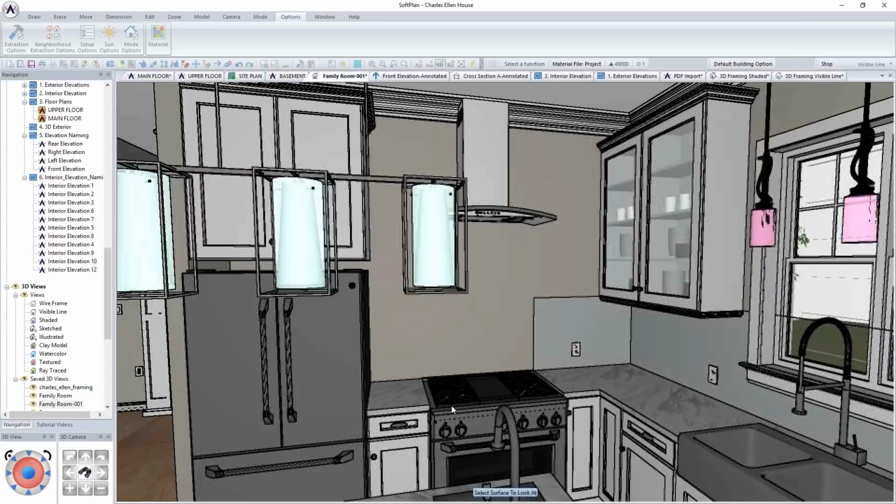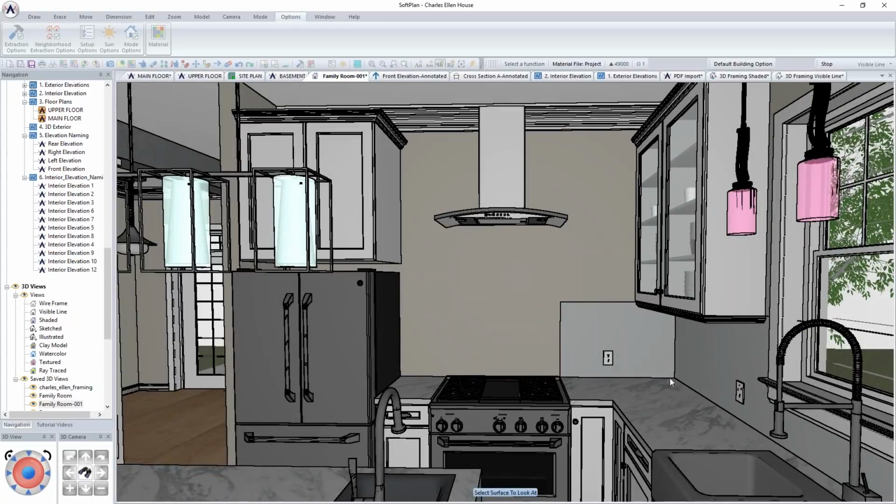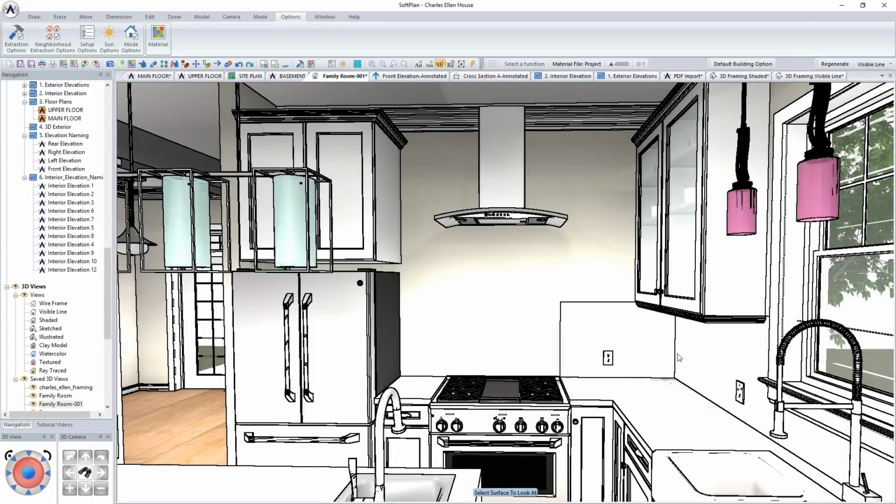And so what in essence you would wind up doing, if you were me, is in a lot of cases, I wouldn't use this option. I would turn it off, and then I would use the interior mode and sketch some sort of a wall covering here, and then I'd modify the height for it, and I would then attach a texture to it.